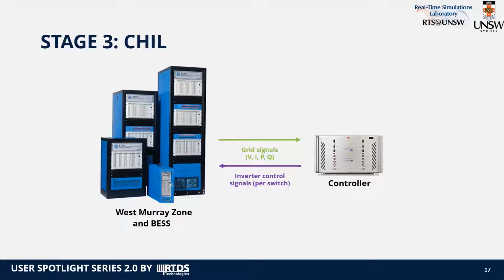The undergoing third stage of the project consists of performing control hardware in the loop when including the controller of the inverter. This additional stage is done as one of the requirements of the funding agency. One option we have is to interface the controller directly to the RTDS simulator through the use of GTAO and GTDI cards. While the GTAO is sending power system measurements to the controller, the RTDS is receiving the fire impulses from the controller through the GTDI card.